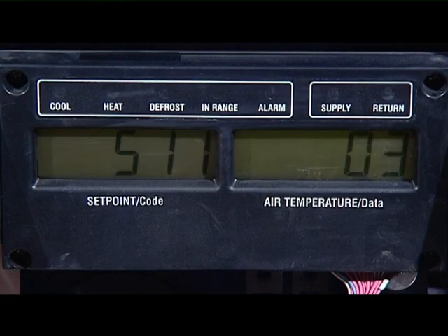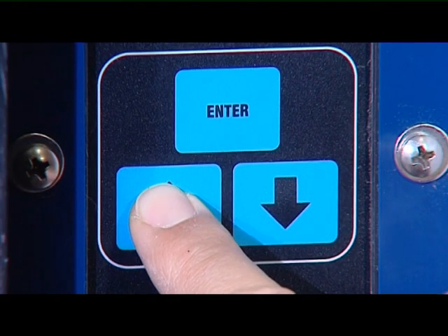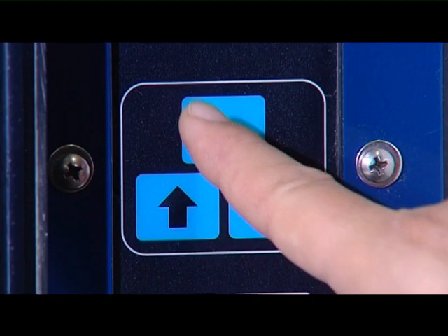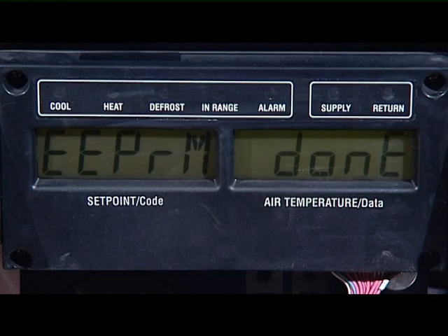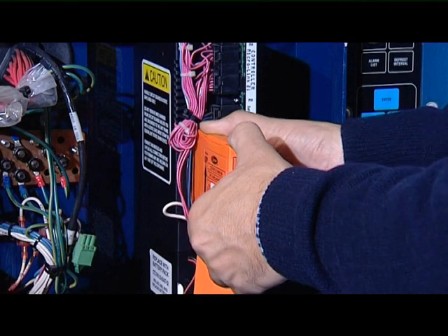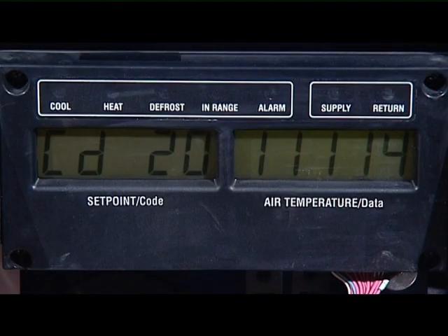The display will show the unit model series in the left window, for example 511, and in the right window will indicate the dash number for a given unit model. Check the correct unit model number on the identification plate and scroll to the correct model number using the arrow key. When the display shows the right model number, press the Enter key. The display will then show EEPROM Done. Switch the unit off, remove the adapter with the card, switch the unit back on again, and verify the number of the unit model has been loaded by selecting code 20.